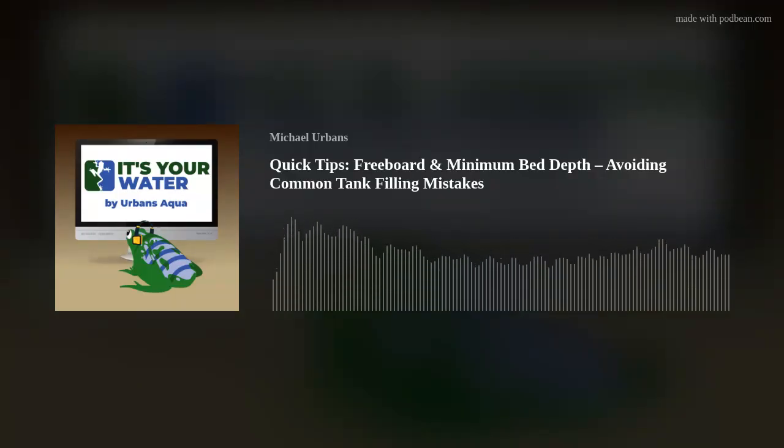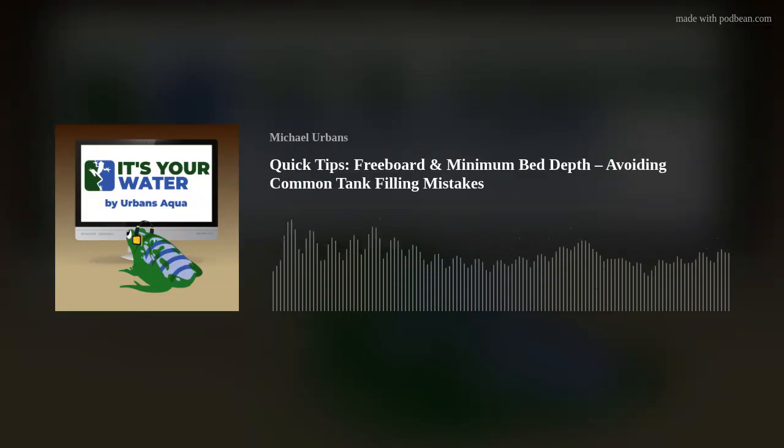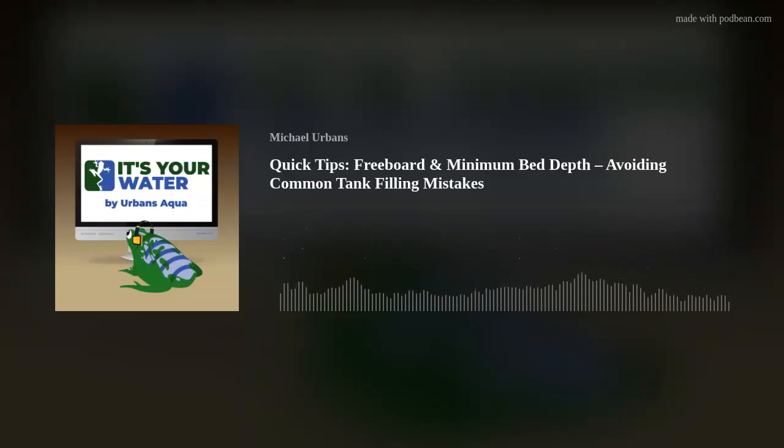People think it's the weight of the media. Cation resin is kind of light. Filter sand is real heavy. Garnet is real heavy. Multimedia is heavy. But no, it's the amount of water in that hydraulic cylinder to actually lift that media.